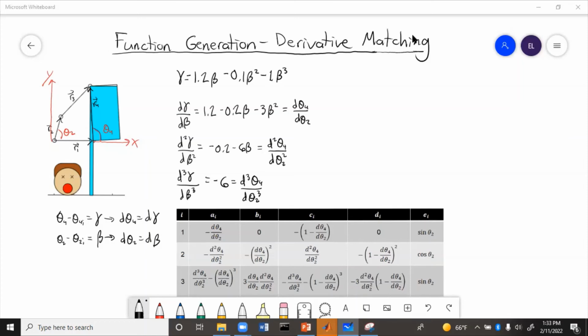I'm going to show you all my MATLAB code, but first, let's specify one more thing, the operating point. For the operating point, I use theta 4 equals 155 degrees, which corresponded to beta equals 50 degrees, or theta 2 equals 110 degrees. So this was the operating point that I took the derivatives at. Using all these numbers, put them into MATLAB. Let's take a look at that.